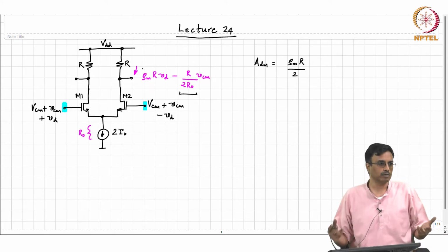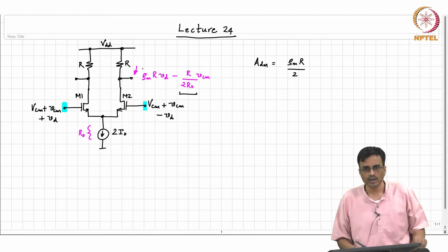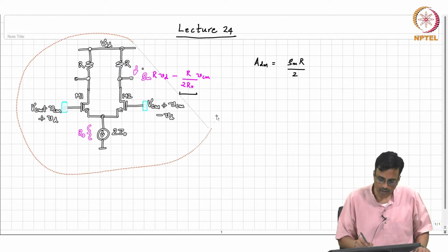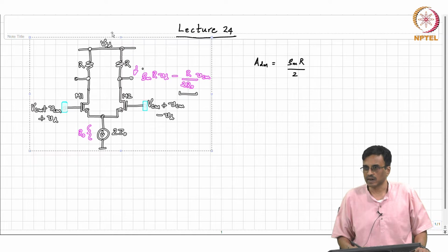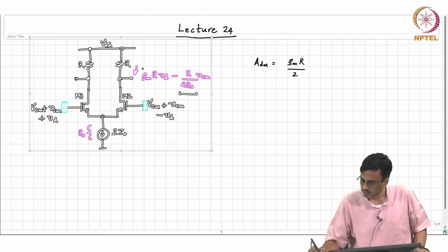So, in the common source amplifier, what did we do? Well, after a lot of discussion, we decided that the best thing to do would be to use an active load, right. So not surprisingly, we have the same problem. So the logical place to start is to work with the same solution, right. So that's what we will do now.